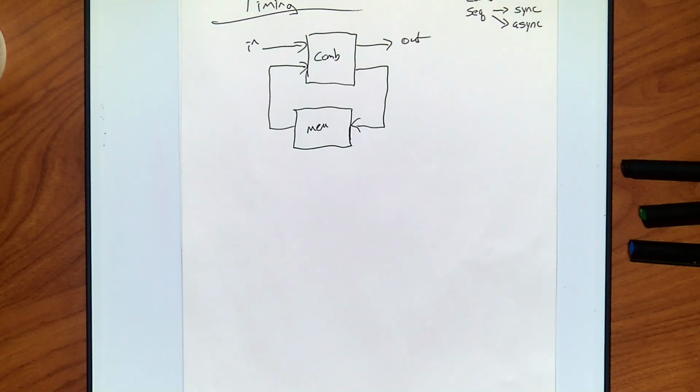So what if I design some logic in front of it that makes it behave exactly as the RS flip-flop did, and then the 1-1 state becomes a flip of the memory? Now you have all possibilities. So half of your input entries are X's, which means you get to pick them when you do the encirclements. That gives you a lot of flexibility. So JK is designed for that: I'm doing a lot of logic, and I want a lot of options for what's happening.